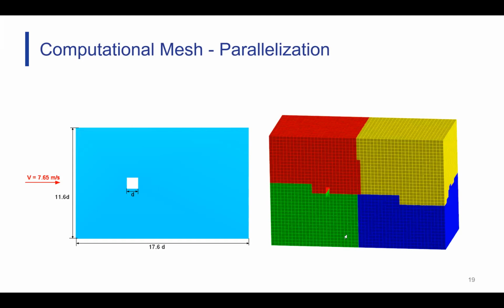Teamwork, nice. Note here, though, that we're splitting the mesh not by volume. So it's not something that we can just roughly divide up into equal parts. And this is because we've refined features. So some parts of the model will have more cells than others. And we want to distribute it in roughly the same amount of cells so that every computer is counting roughly with the same intensity. Otherwise, well, that just wouldn't be fair. And again, FlowVision will do the split automatically for you.